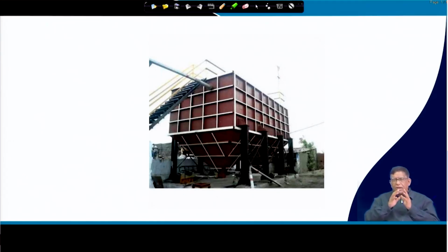So, a bunker, as you have seen in the first one, can be on the ground, as in the grain bunker. It can also be underground: by underground excavating or mining and excavating the rock, you create a structure and then you give the liner, and there you keep the material and make the arrangements for taking it up, and you can fit externally fitted structures, and that will become a bunker in the underground. And this is an elevated structure.